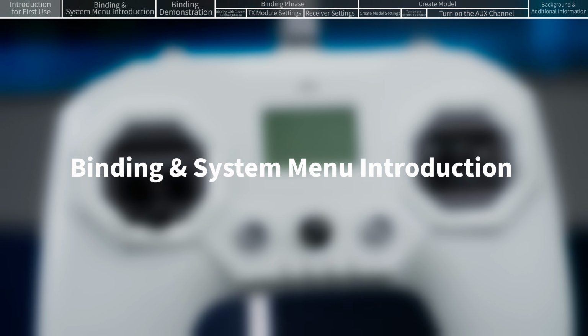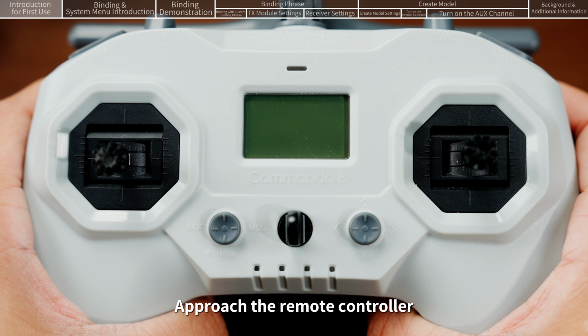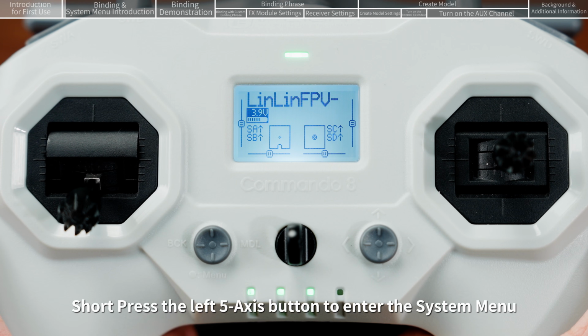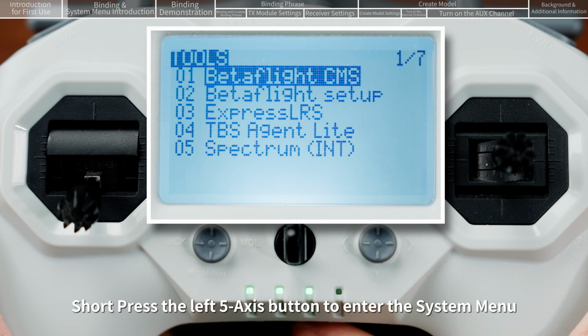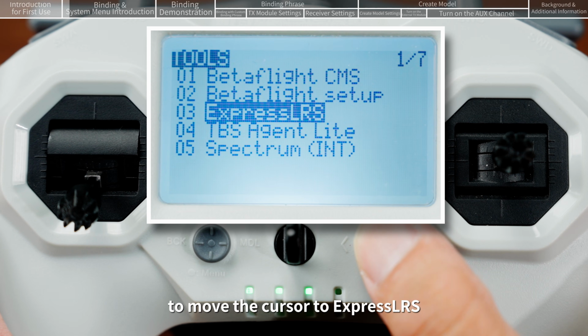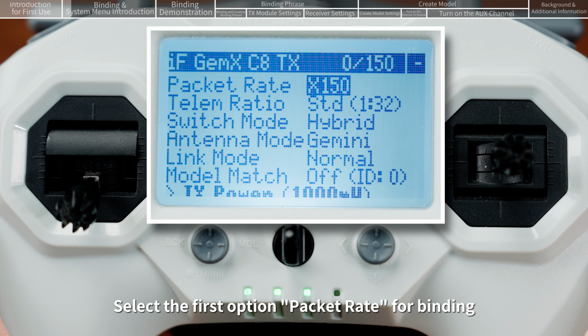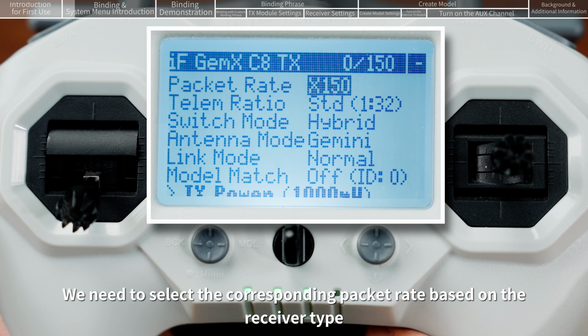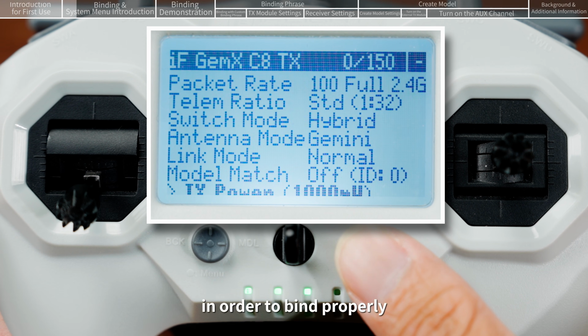Binding and system menu introduction. Approach the remote controller. Short press, then long press, to power on. Short press the left 5-axis button to enter the system menu. Short press the right 5-axis button to move the cursor to Express ELRS. Select the first option, packet rate, for binding. We need to select the corresponding packet rate based on the receiver type in order to bind properly.